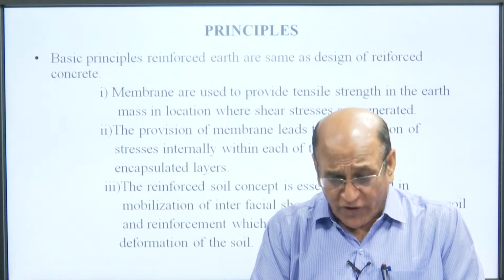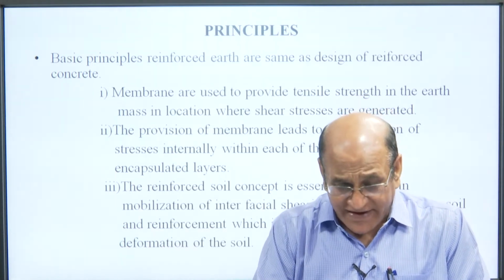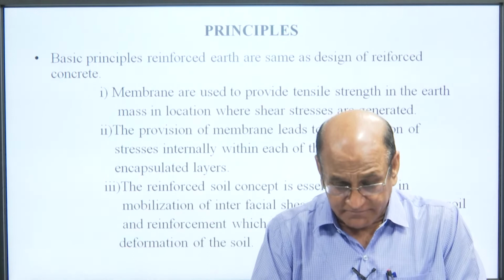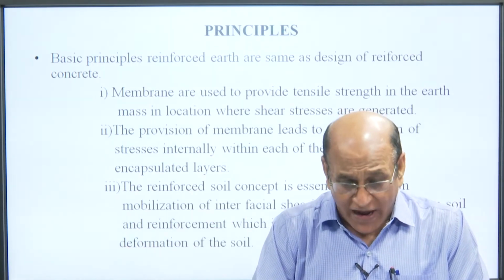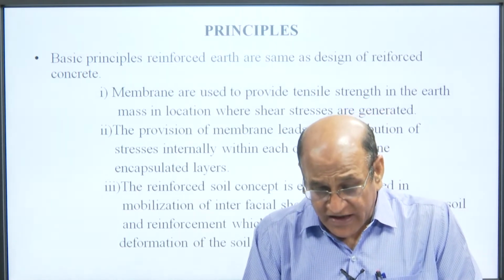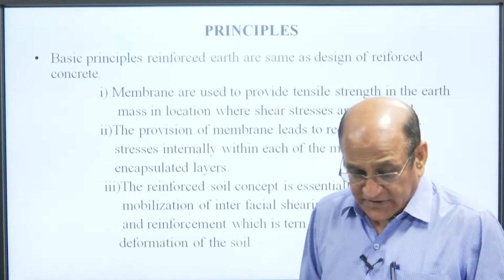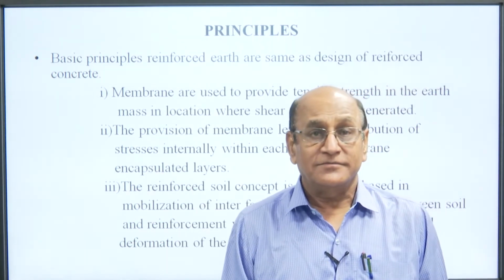The reinforced soil concept is essentially based on mobilization of interfacial shearing resistance between soil and reinforcement, which serves to restrain the lateral deformation of the soil.